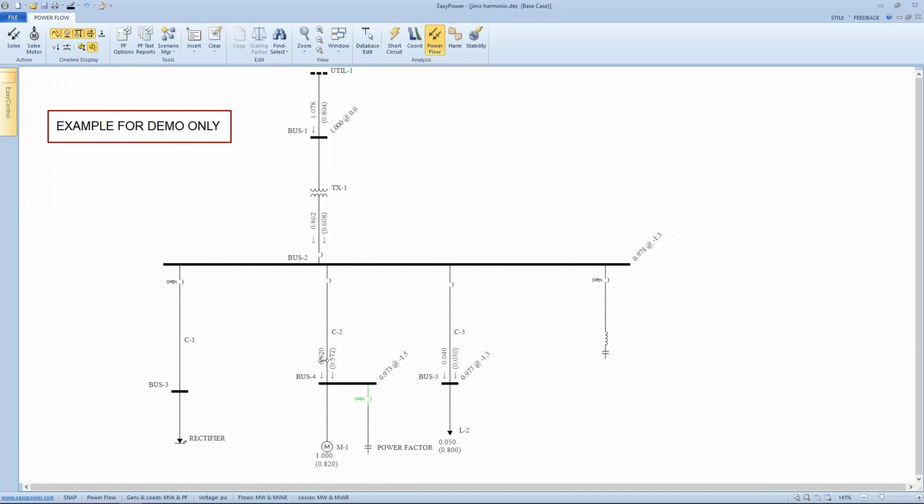And what we can see here, just as an example, is the real power and reactive power that has to be delivered to the motor for it to be able to run at its performance level. There are two reasons to put capacitors in the circuit. One is to correct the power factor itself, and the other is to bring up the voltage, because with this load and the losses involved in the system, the voltage is going to droop to the point that we have less efficient motor operation because of the low voltage. So the solution at the time was to put in power factor correction.